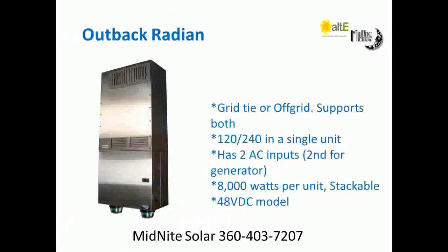So there needs to be a voltage sensing relay in there that will disconnect the grid tie inverter when the batteries get full. Now, on our pre-wired systems, that's all done automatically for you. All you need to do is verify the programming and run a fail-safe test yourself just to verify everything is doing what it's supposed to do before you leave site. But that disconnect circuit is all built in.